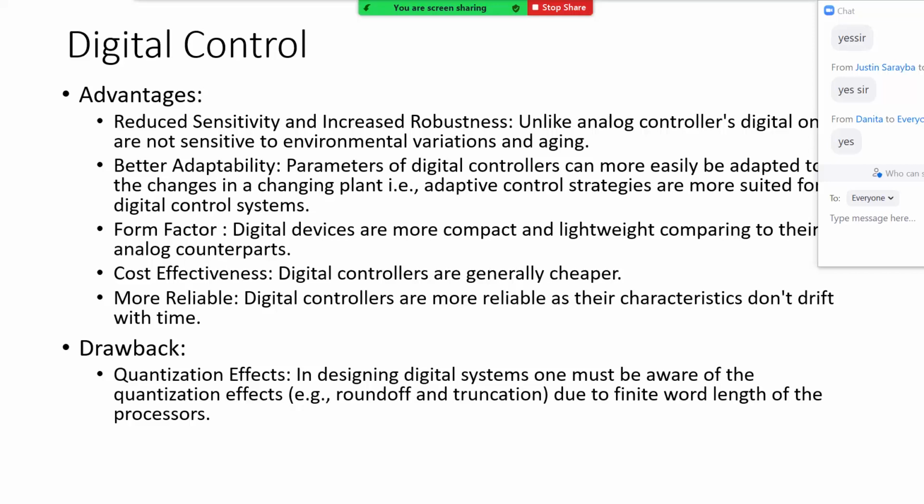However, with a digital signal, it's zeros and ones. So even if my signal is represented by a voltage within the range that will be decoded as 1, it can have some noise and still be decoded as 1. And of course, I can always make sure the signal is correct with error detection or error correction, etc. So with a digital signal, we are more immune to noise.